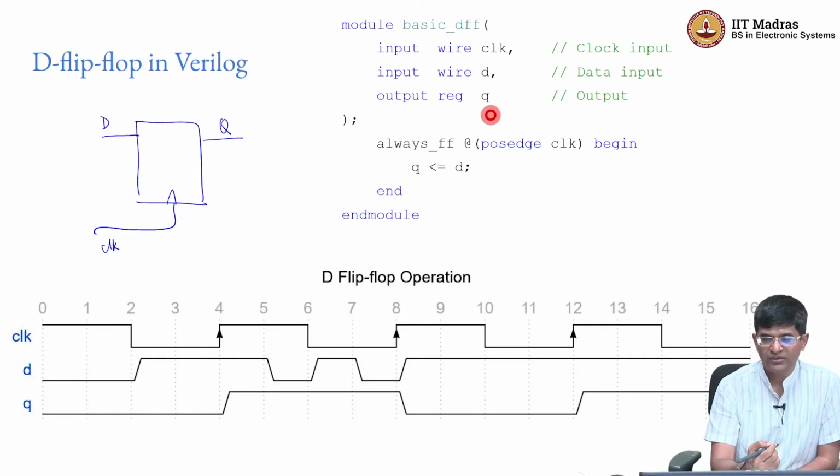Now once again, with SystemVerilog I wouldn't be using wires and reg over here, I would just be declaring them as logic, right. But as I said, I'll be using these interchangeably, switching back and forth between the two. It's probably a good idea to get used to both of those, but in general, for the most part, we'll try and stick to logic to avoid any possible confusion with wire and reg, except when we are trying to make a point, right, that you can get confused. So be prepared for it. Make sure that you understand both of these, because it is very likely that you will encounter some Verilog code at some point in time that still uses the older conventions and therefore works with wire and reg rather than with logic.